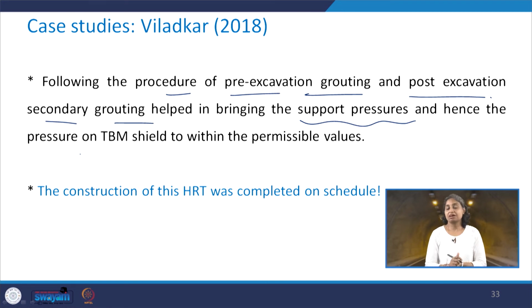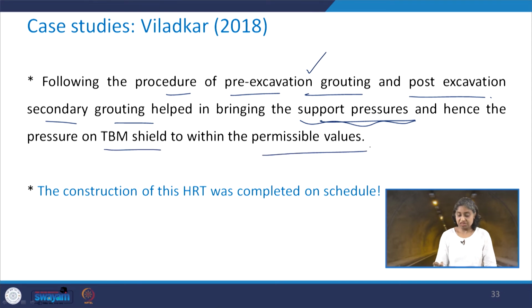See, without this grouting, the support pressures were coming out to be very large, beyond the permissible value. So what was proposed was to go for the pre-excavation grouting and also the post-excavation secondary grouting to bring these support pressures and therefore the pressure on TBM shield within permissible values. And the construction of this HRT was completed on schedule. That was one of the wonderful things.